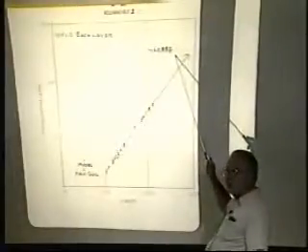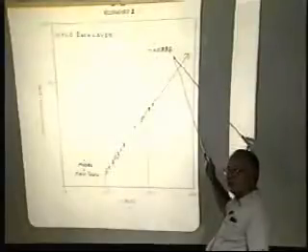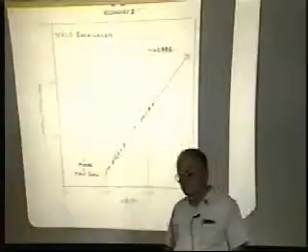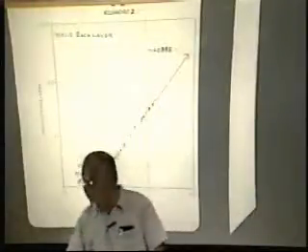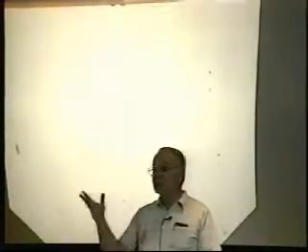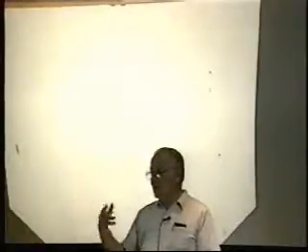And the slope, even though there's no non-Darcy flow at all in any layer in the model, any layer, it's got an n value of 0.886. That was a surprise. And if I hadn't started out and said, well, let's keep this simple, don't use non-Darcy flow in trying to do your superposition of all the KH and skin, otherwise you've got different numbers. And you would assume that there was non-Darcy flow in the problem.